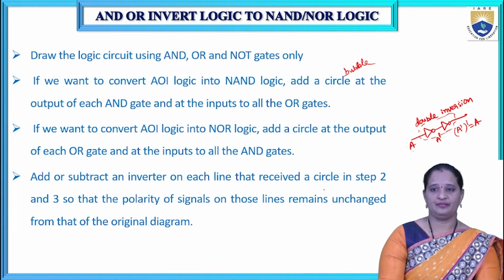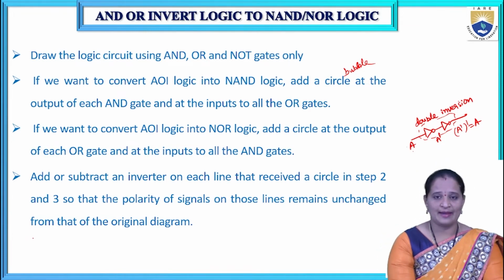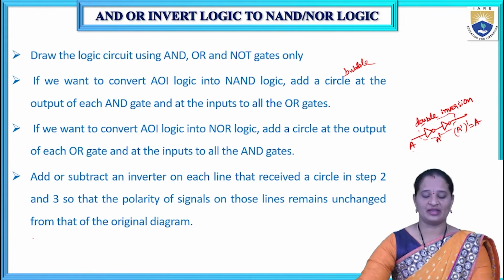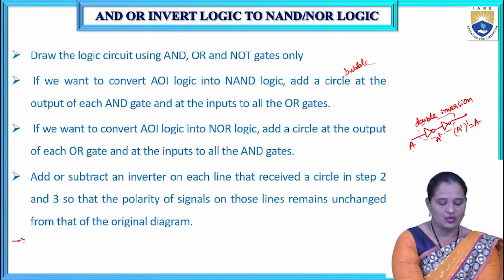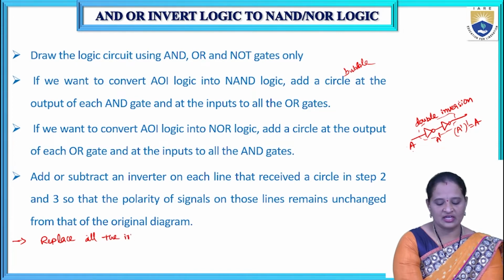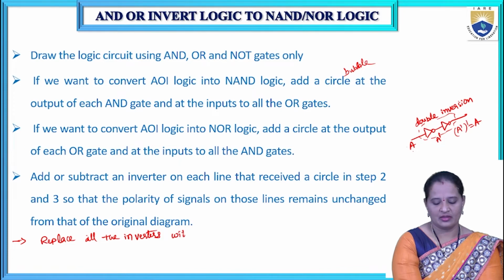And finally, the final step of this NAND or NOR implementation is we need to replace all the inverters with NAND or NOR gates.